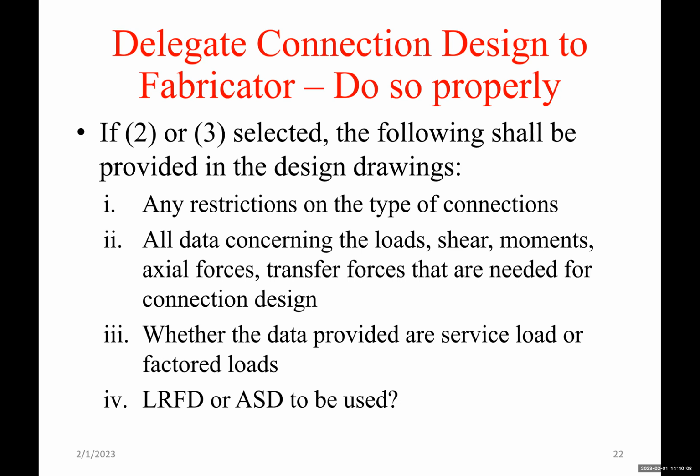Indicate whether the data provided are service loads or factored loads. This is very important, so you have to indicate, are these loads factored or not? Whether LRFD design or ASD design is to be used has to be dictated by you as an engineer. The fabricator knows both, but how you design the building and what forces these are, you indicate in your notes. So connections need to be designed using the LRFD procedure or ASD procedure, etc.